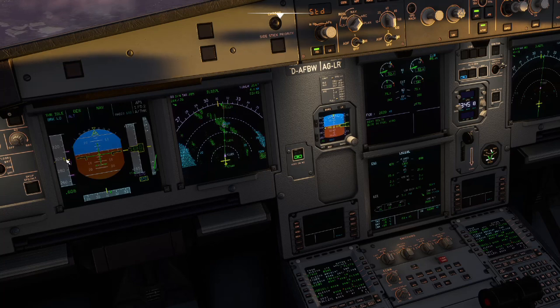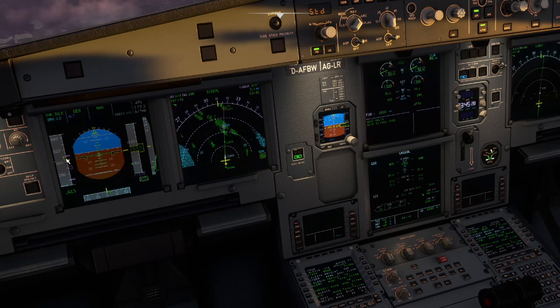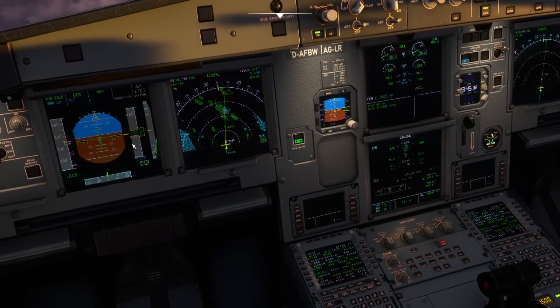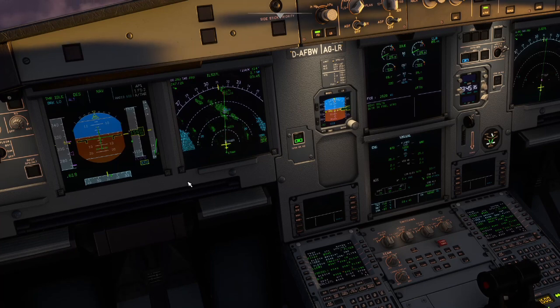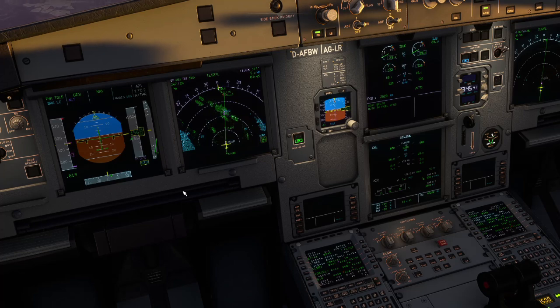Got heaps of speed margin to do that, push the nose down and take the speed increase to catch back up, which is exactly what it's doing. It's using that bit of speed. Speed generates a little bit of extra drag. And there we go, just about back on that profile, and then it'll start slowing the rate of descent down, and the speed will trickle back.